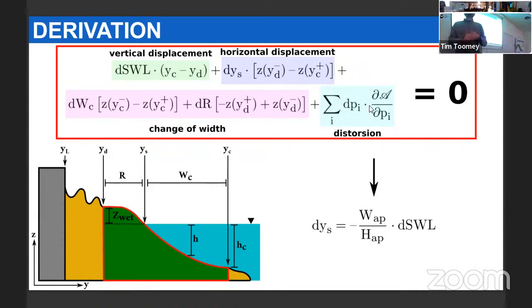Or now people even use drones, like toy boats, remotely controlled with an echo sound. Usually for the shallower part you move with a GPS, and for the deeper part it's a boat with an echo sound. So actually the parameterization of profile that, for example, Dean and Bruun used is based on actual surveys that were done in the field.